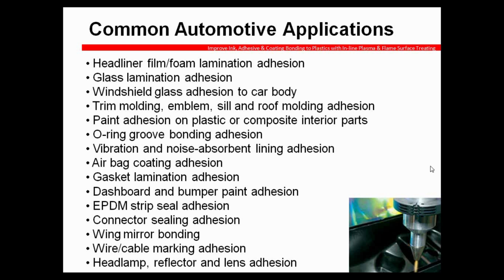Rubber seal adhesion, that's another thing as well. Being able to apply different types of seals and gaskets to metal components, trying to get better bondability between two materials that just really don't like to adhere. Whether they're not adhering at all or we're just trying to get a better pull strength between the two, that's something we've been able to address and solve for quite a few customers out there.